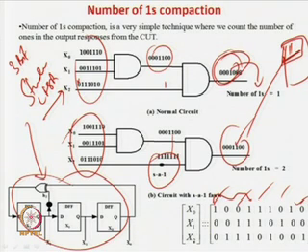Another case may be that if you are using only these 4 vectors with the compaction technique, then your coverage is very high. Then you are at a great design, and your life is good, because by using only these 4 consecutive patterns you can apply them very quickly from your LFSR, and all the faults are tested by the compaction technique.